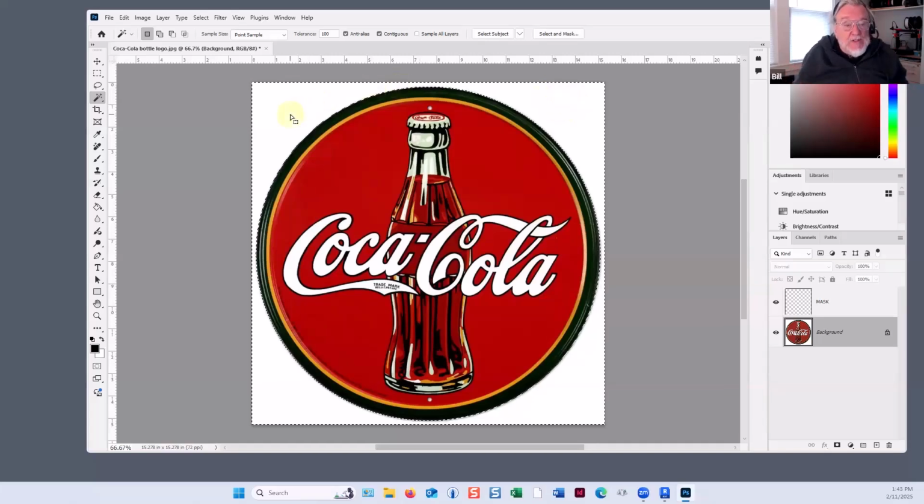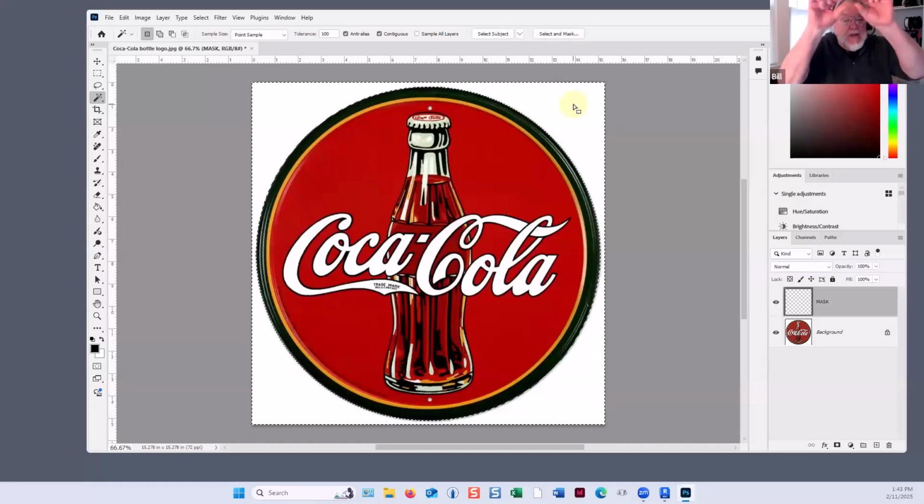But I actually want to do the painting. I'm going to paint into these areas onto the masking layer. So now I'm going to make it active. And actually, when I selected it, it didn't pick pixels per se. It didn't pick like this white pixel. It picked a region. So now I'm just saying, think of the region as being up on the masking layer. And I'm just going to paint black into here that will mask the white when we get it into Revit. I didn't invent this. This is the way it works.